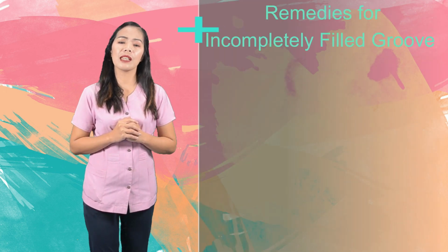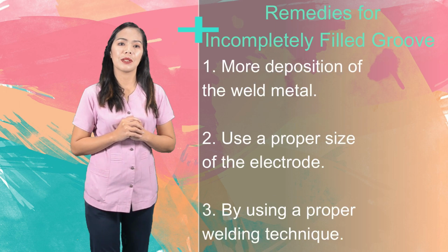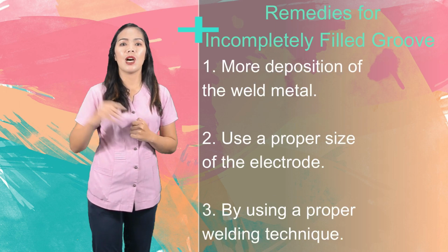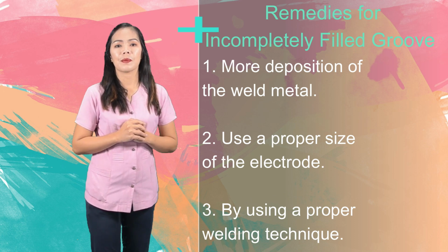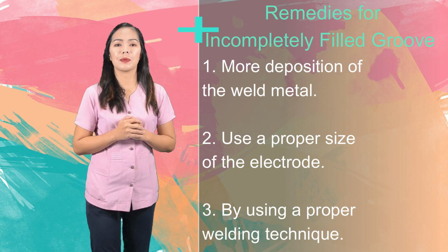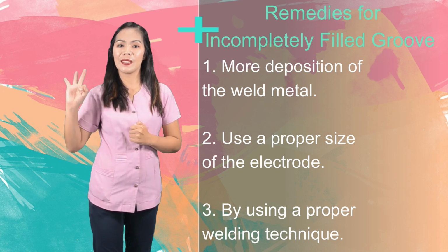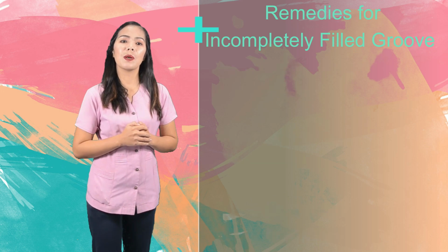Remedies for incompletely filled groove. Number 1. More deposition of the weld metal. Number 2. Use a proper size of the electrode. Number 3. Using a proper welding technique.